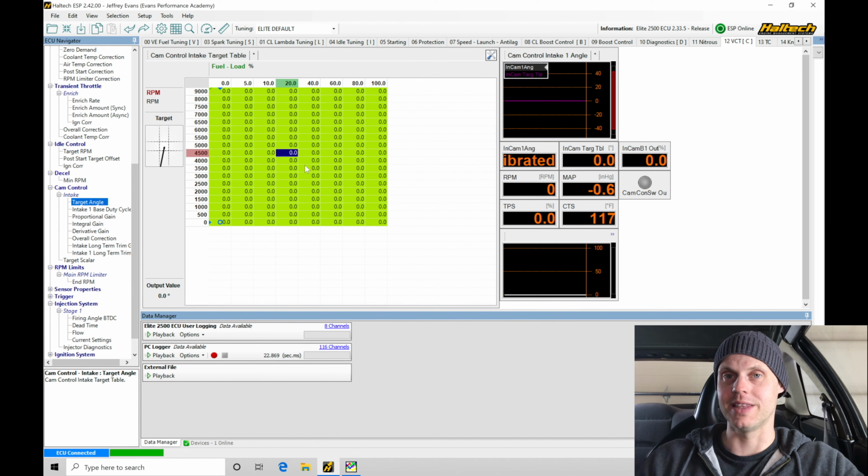So we're going to find in that situation where we're going to have that exhaust scavenging effect, low and mid-engine RPM, our exhaust pressure is going to be the lowest. As we get up into high engine RPM, our exhaust pressure is going to increase. It exponentially increases. If we were to draw a line, it would start off low and then have a rapid rise in the actual line of exhaust pressure if you were going to be mapping it out and actually logging it and taking a look at it.